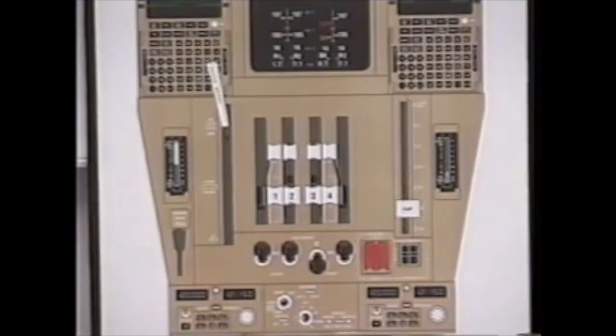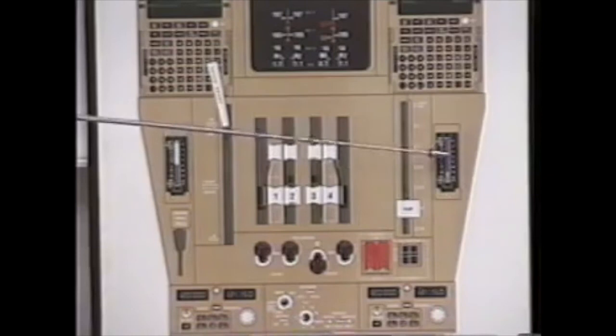Continuing our review on the center aisle stand, moving further aft, our stab position indicator for both the captain and first officer. Remember, stabilizer trim is pressurized by hydraulic system 2 or 3. One of those 2 systems must be pressurized in order to move the stabilizer. The airplane has the ability to expand a normal green band range forward or aft for airplane nose down and airplane nose up based on the amount of weight on the nose wheel and the value of the CG you type in on the takeoff page.